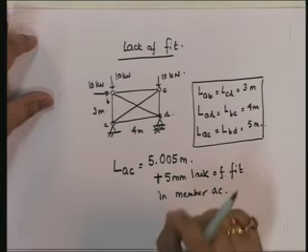And to do that, I am going to forget about the fact that you have a loading on the structure. You see, I am taking the problem as two parts. One part is finding out the forces in all the members due to the loading alone. That I have already done last time, so I am not going to repeat that here. What I am going to do is find the additional effect of this lack of fit that I have because member AC is 5 millimeter longer. That is the only problem that I am going to be solving here right now.